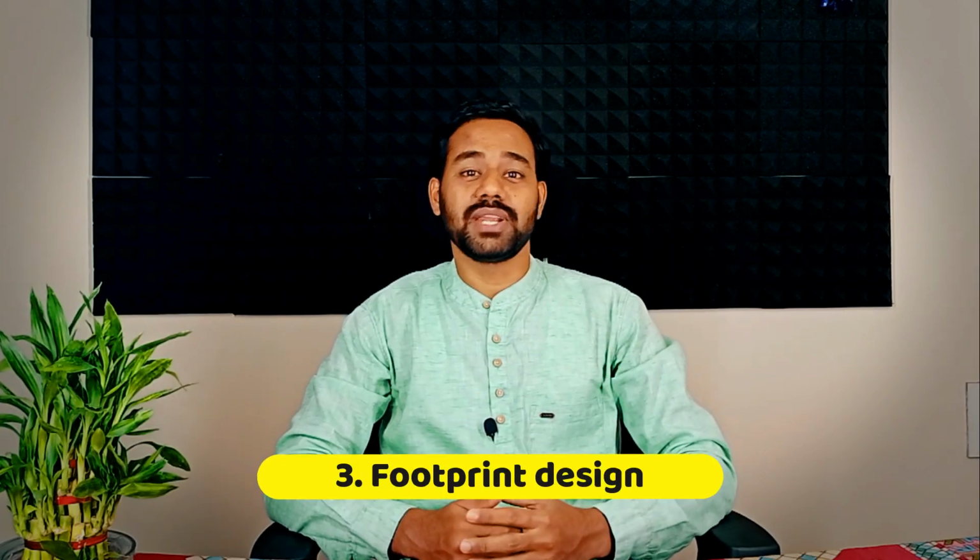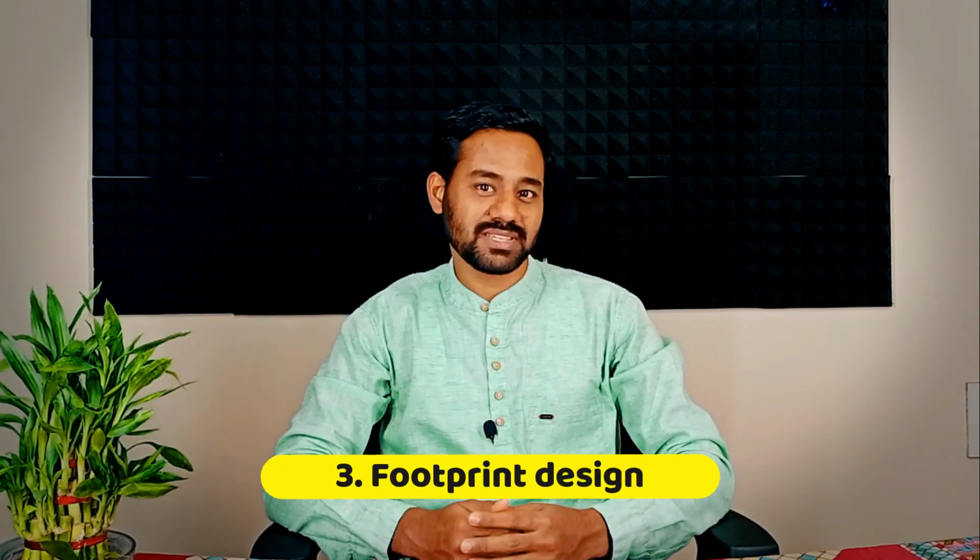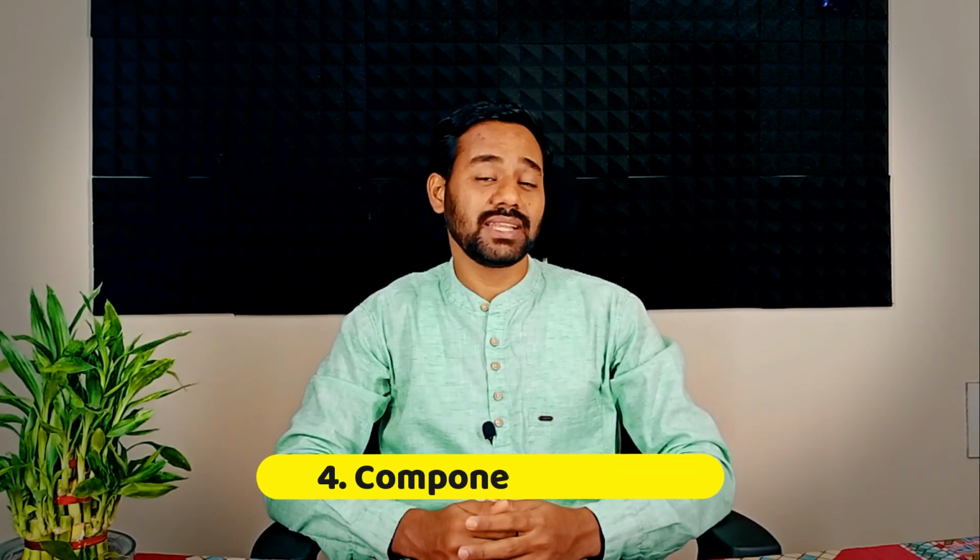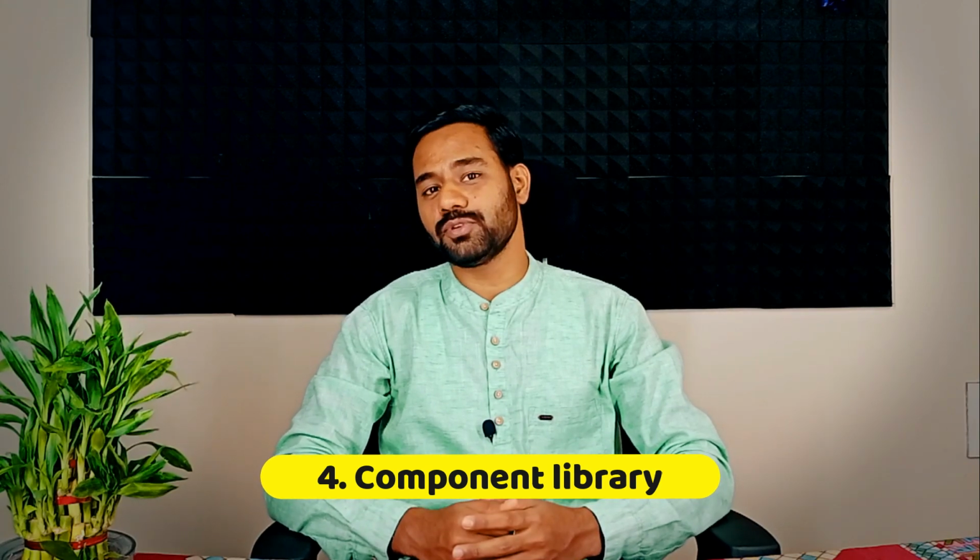This schematic symbol is exactly the same as in the previous tutorial, when we designed the 7805 schematic symbol in our second tutorial. Third step is creating a PCB footprint using IPC standards and Cartesian geometry, with the different package that we have selected as the SMD IC of 7805. Last but not the least, the fourth step is combining the schematic symbol and PCB footprint to create a component library, so that whenever we want to use it in any project, we can use it as a component library.